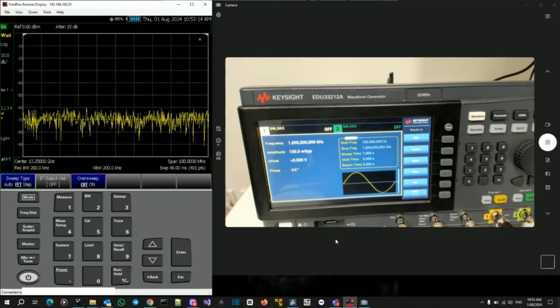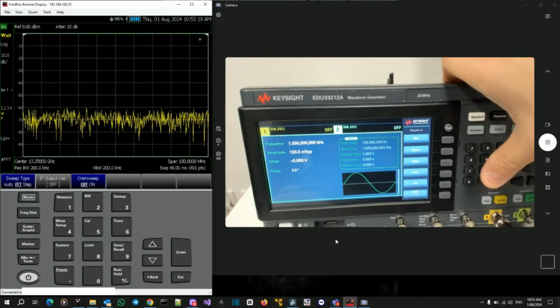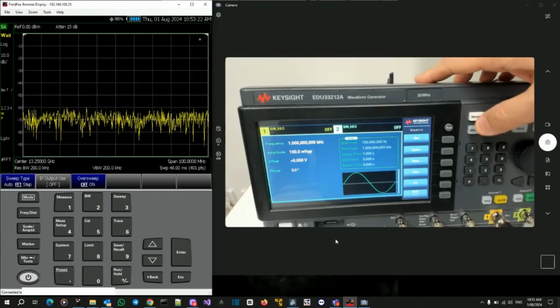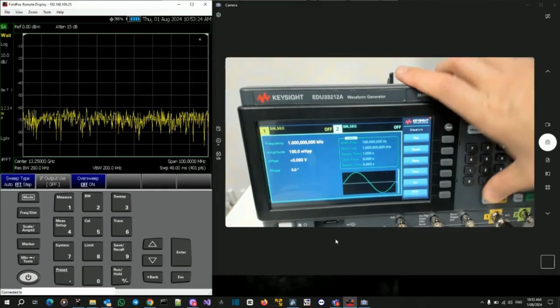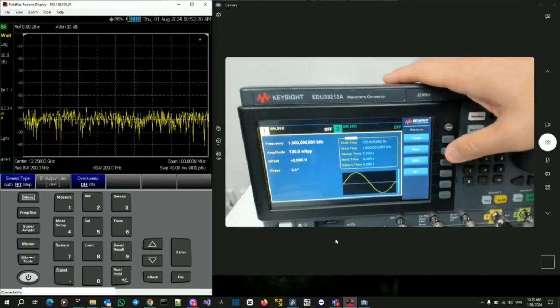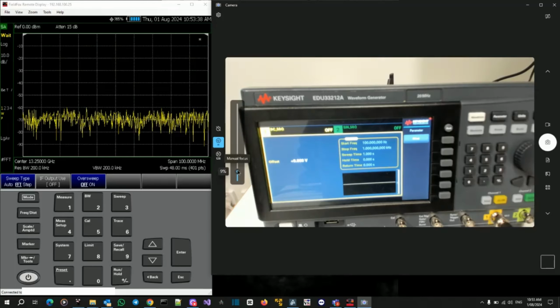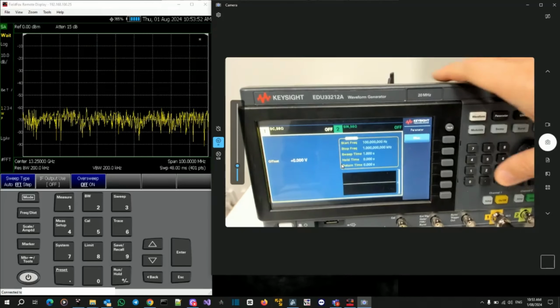Let's set the waveform generator to a DC trigger of 5 volts. Let's go to waveform. Oops. Let's go to setup for channel 1, waveform, go to more, and DC. Let me try to focus this a bit better so that you can see. Okay, because of the lighting, can't really see that. What you're seeing over here is the setup for the offset. So the offset, we can set it to 1.8 volts.